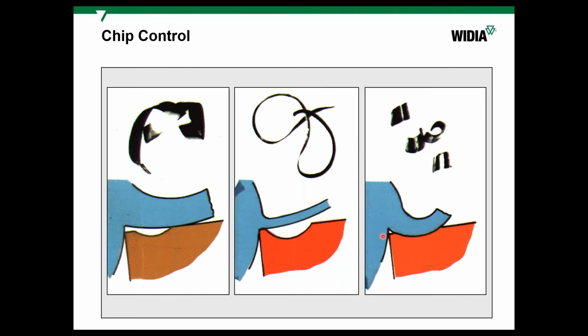And here you can see one of the recommendations we talked about yesterday. Basically, the feed per tooth should be greater than the T-land. If the T-land is neutral or negative, in order to let the chip breaking process work, the chips should go into the chip breaking profile in the correct way. Not like here, where this T-land resists the chip going inside, and it doesn't have any affinity to be broken.